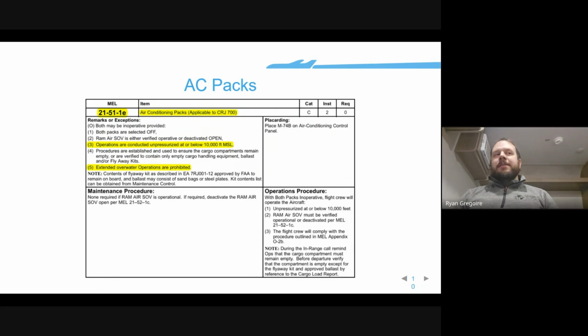And what that entails is the airline has reached out to, for instance, if you're dispatching an A320, Airbus, and said, this is the damage on the aircraft. This is the extent of the damage. You know, there was major bird strike damage to the nose cone of the aircraft. We have to move it to a sheet metal fab base in order to get it fixed. Can we get a set of operational restrictions outside of the CDL manual so that we can ferry this plane?